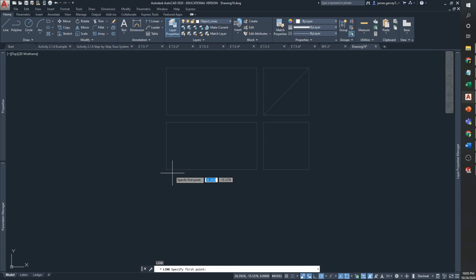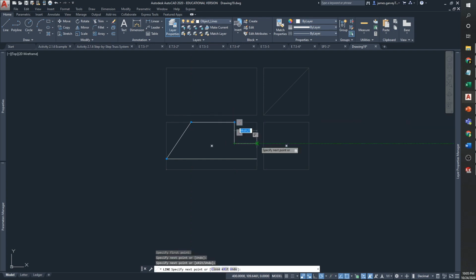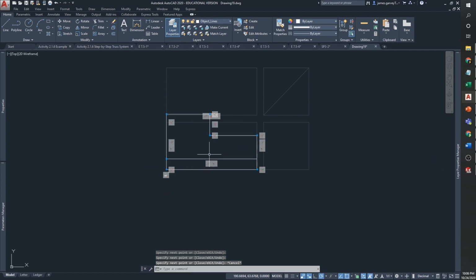You can put in your dimensions the way they list on the drawing, but because we're applying those geometric and dimensional constraints, I can just make the shape that it should approximately be and apply those dimensions later. So I'm going to just do quick and dirty here. Place my lines in for each view up to there.